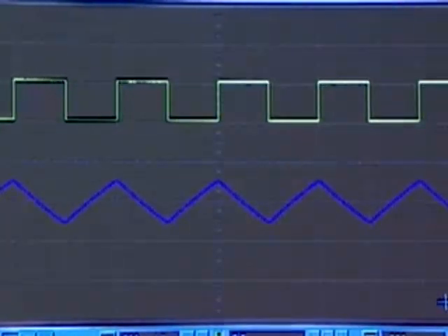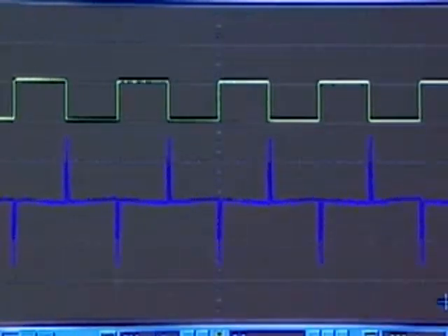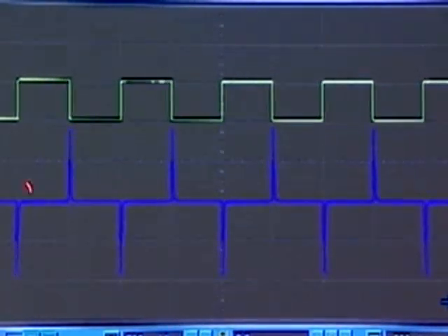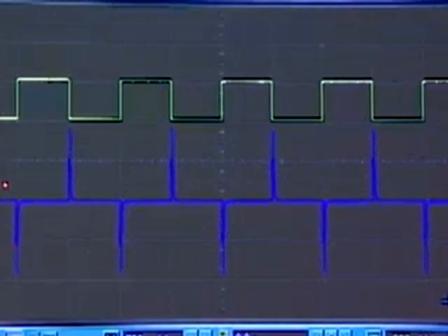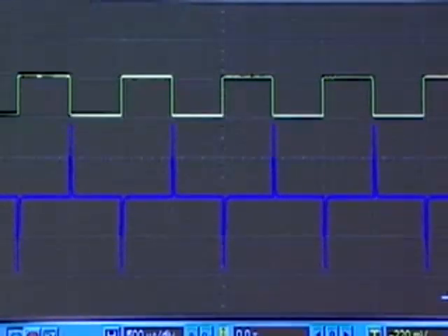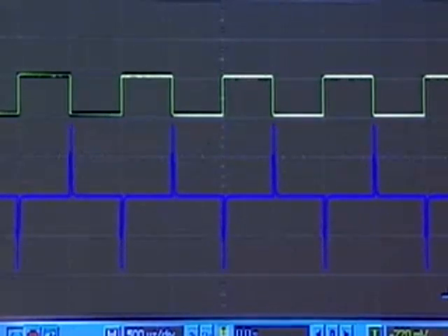And we'll do the same thing for a differentiator. For the differentiator, I input the square wave to this differentiator circuit, and I get this: whenever there's a sharp rise, I get this huge negative spike and a positive spike because of the minus sign. So this is the differentiator circuit when I feed this into the op-amp.